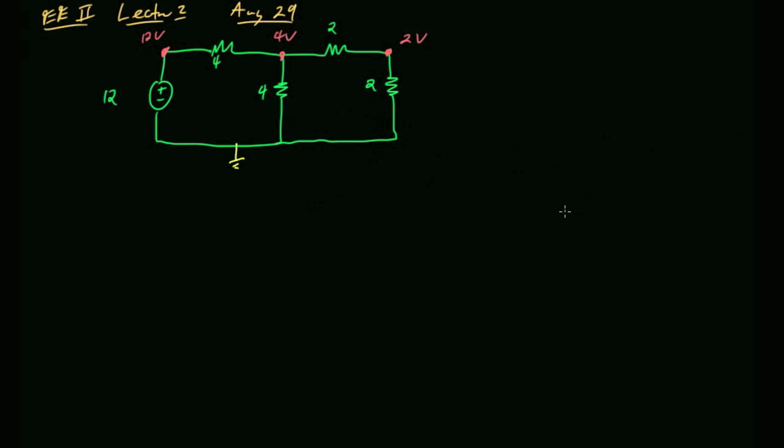Okay. And we're starting to ask some interesting questions. Like, for example, I asked if we changed the resistor value here, would we draw more or less power from the power supply? So does anyone remember if we decrease that resistor, do we draw more or less power from the supply? More. And what's the intuition for that? Right. There's less total resistance, which means there's less stuff impeding the flow of current. So you can have more current. If you get more current out of the same power supply, you get more power.